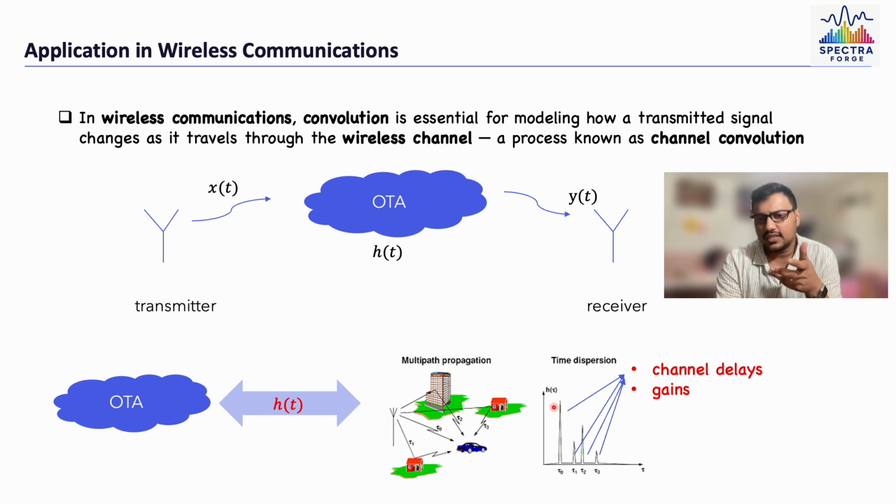So usually the line of sight, or the first timestamp, will have a higher power, because it has not gone through any reflection or scattering. It's direct line of sight, which will have maximum power. It's not attenuated by any blockages. But there may be a delay because of the propagation, because of the distance between the transmitter and the receiver.